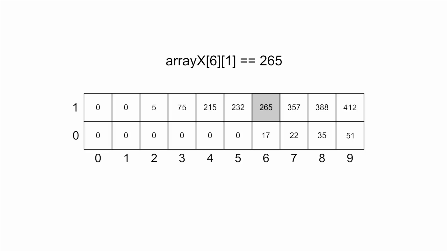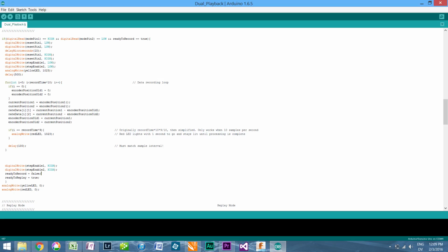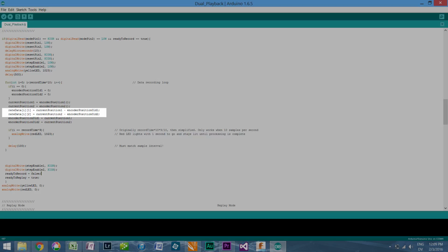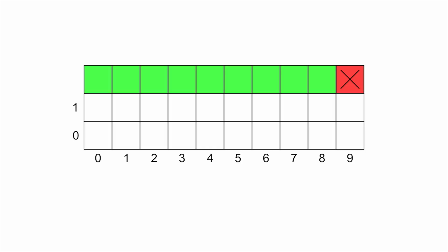So my problem is with this last spot in the array, the very last one. And the reason why there was a problem was that if you look at my code and you come in here, you can see that I'm using 1 and 2 because it's motor 1 and 2, but it's position 0 and 1. So I was actually out of the array up here in Fantasyland. And the thing that made this so difficult to catch was that it worked fine for all of the previous positions. And I'm sure there's a good explanation why that last one was changing randomly, it wasn't random.